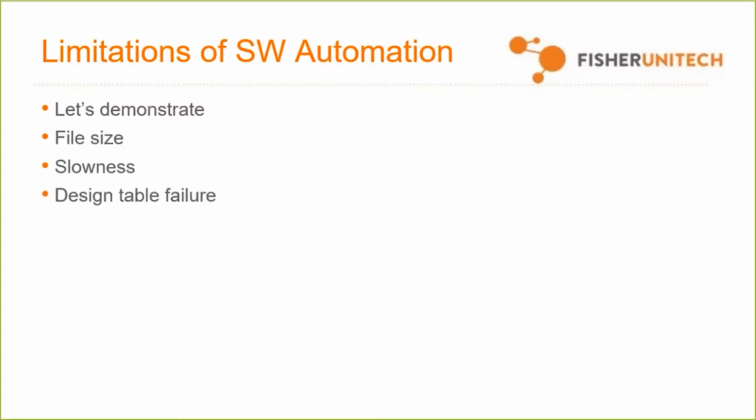You might see design table failure. As an example, my design table went out well past column C, CA. And you might accidentally forget something and delete it out, and then you go back, and then you try to add something to your design table, and the sucker's not working. I can't tell you how many times that happened with this assembly, and it was very, very frustrating, to the point where I had to actually redo the entire assembly because I couldn't get it to work.